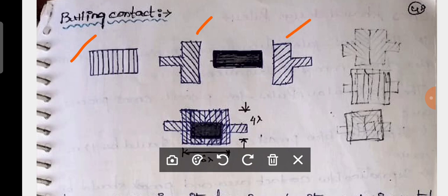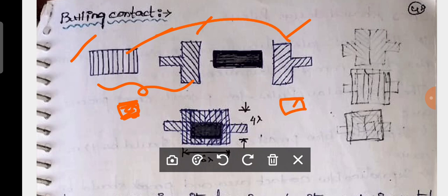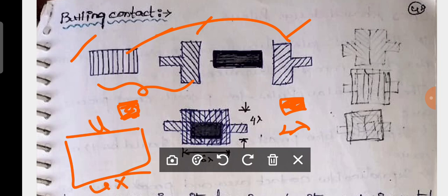Now you can observe that you have to connect these two. When metal is connected to polysilicon, you are having a contact cut of 2 lambda. When metal is connected to diffusion, you are having a contact cut of what? 2 lambda. Is it clear or not? That means one more extra 2 lambda is present. Actually, what is the contact area? That is 4 lambda by 4 lambda. Is it clear or not? When one more contact cut comes here, then this length is going to be changed as 6 lambda. Is it understood?